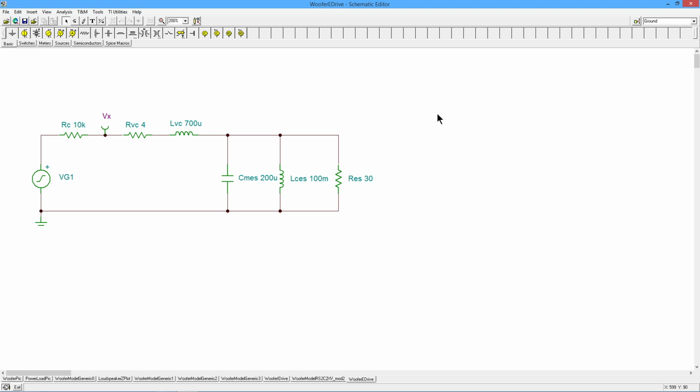Now your resonant frequency, Fs, will occur at a peak. As you change the input frequency, you're starting down below, like maybe 10 hertz, and you start cranking that frequency up. You got to do this kind of slowly. You'll see that voltage grow. That sine wave will get bigger and bigger in amplitude. And then it'll start to fall off again, right? So wherever it maxes out, that's Fs. Another thing you can do is take a second probe, put one on the generator, and when the two are perfectly in phase, that would mean the circuit's resistive. When they're perfectly in phase, that's another way of defining where Fs is. So you record that frequency.